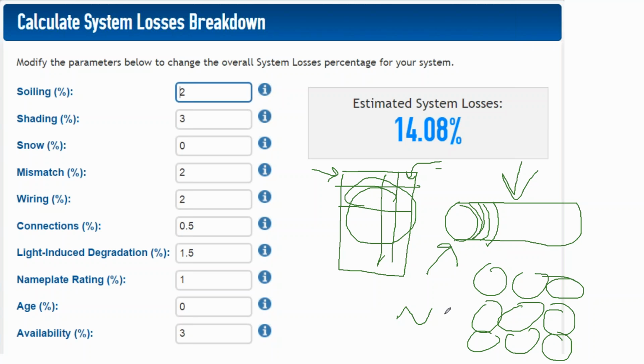Now, the way it shakes out in today's industry is they test the solar panels, and they even test the cells and do a little bit of cell sorting. The higher efficiency cells comprise that 320 watt panel, and the lower efficiency cells comprise the 290 watt panel, and all the cells are the same size, so all the panels are the same size. But out of the same production run, you get a higher efficiency panel that might be sold to someone in New Jersey, then you get a lower efficiency panel, and that might be sold to someone in Mississippi at a lower price point.